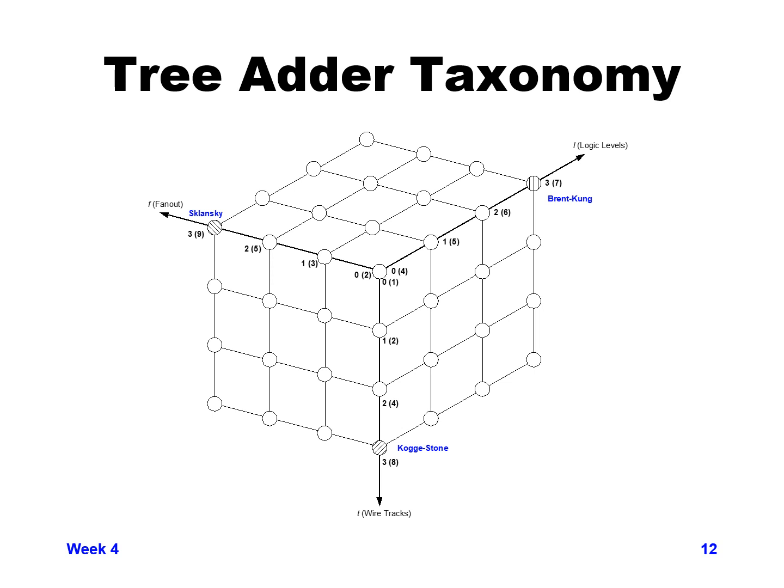When you calculate 2 to the third is 8 plus 1, gives you a fan out of 9, but your logic levels is 4 because it has L equal 0, and your wire tracks is 1 because T is 0. So this gives you a way to map out what the trade-offs are between those 3 different adder styles, where you're trading off fan out versus logic levels versus wire tracks.